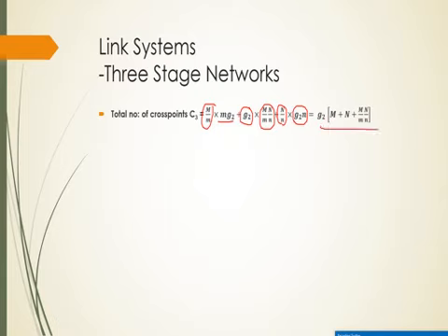Now as we are discussing m greater than n, that is, for a concentrator, the number of links, whether it is A or B, will be limited by the lower value, which in this case is the outgoing trunks. Therefore, to obtain an optimum solution, we can equate the number of links to n.